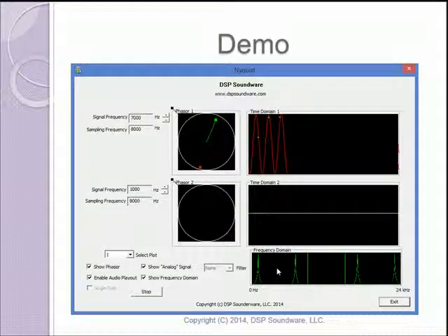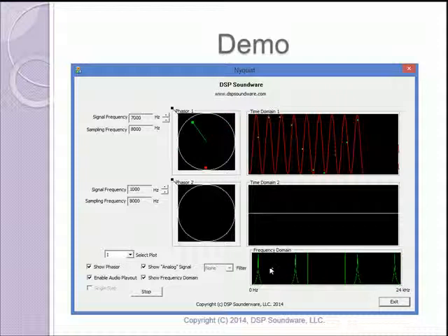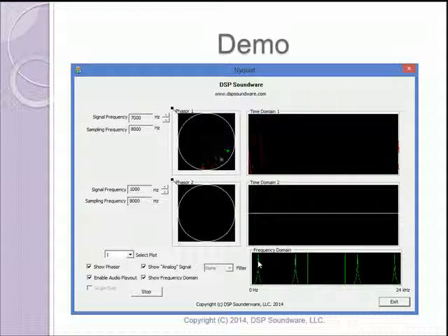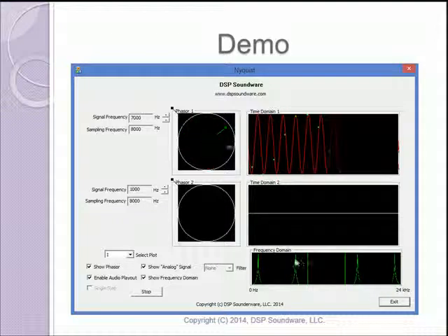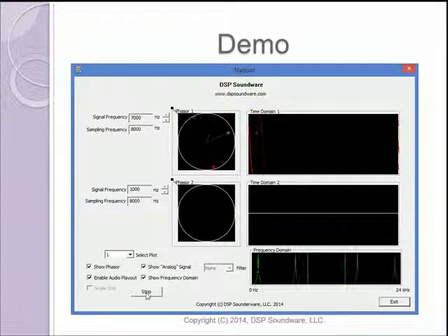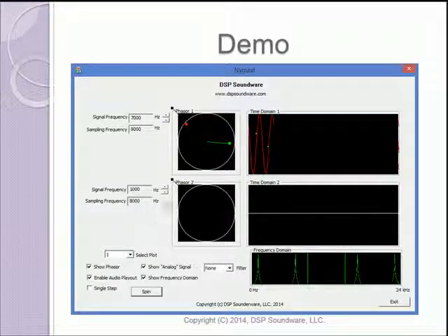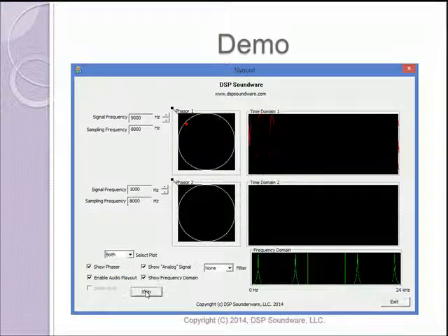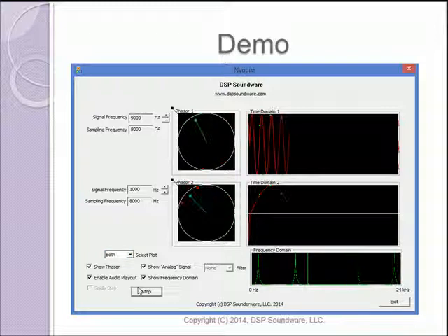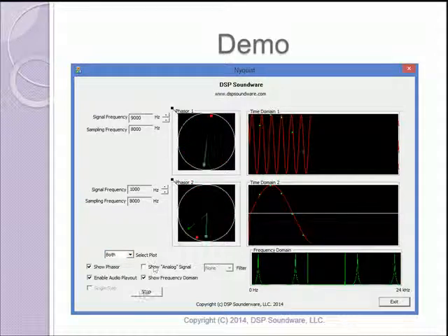And what we know from our DSP courses, that's aliasing. We can't really tell the difference except in phase between 1 kilohertz and 7 kilohertz. And in fact, if we look at 1 kilohertz and 9 kilohertz, they look identical, even in phase. And let's do that. Both plots. Set this one to 9 kilohertz and resume. And I'll turn off the analog signal and it'll be even clearer.